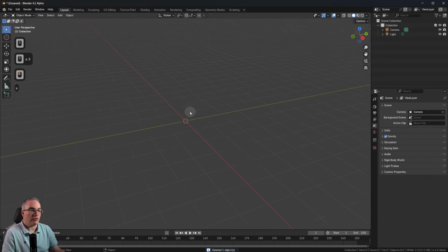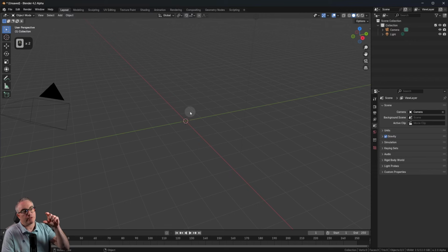We are not going to use the default cube. So let's think about this little bottle for a second. We're going to think about the glass part at the bottom first. There's different ways you can model this. You can start with a circle, extrude that up, and then model the mesh. You can start with a cylinder and model the mesh. You can do the classical sub-D modeling workflow. Or you can just model the outside shape of that bottle and then use a modifier to spin that around and even give it some thickness. And that is what we're going to do today.